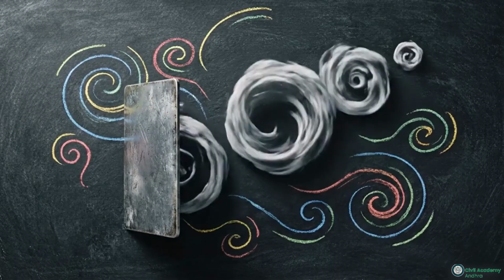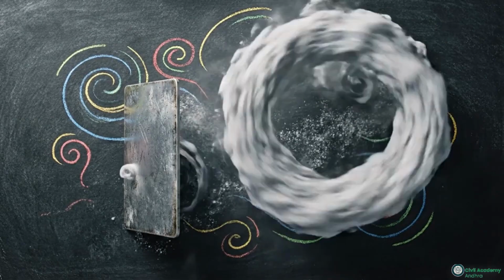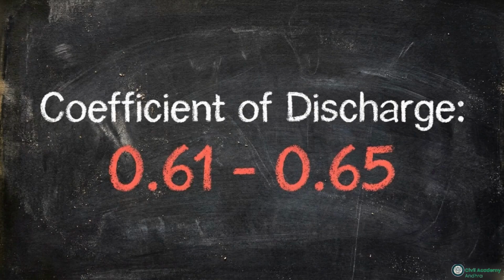Without a gently angled cone to guide the expansion, massive flow separation occurs, creating chaotic, energy-destroying eddies in the dead zones directly behind the plate. This permanent head loss slashes the mathematical efficiency. The device's coefficient of discharge drops heavily to between 0.61 and 0.65.